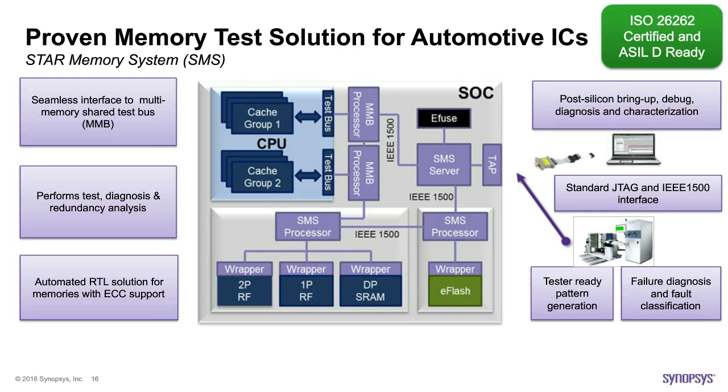And gladly, we do have IEEE standards that have been developed to help us with this communication. We do have IEEE 1500, which is an IP level standard that does a very good job for this purpose. We do have 1687, another IEEE standard, which is meant for hierarchical level testing, that is, switching between different levels of hierarchy, up to the top level where you see this TAP, that's the IEEE JTAG 1149.1, which is again meant for this purpose, to access the infrastructure and handshake with it.